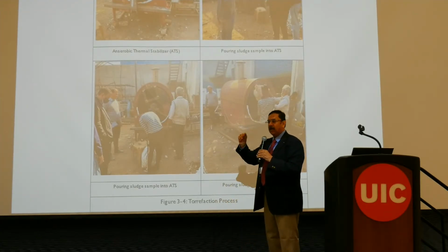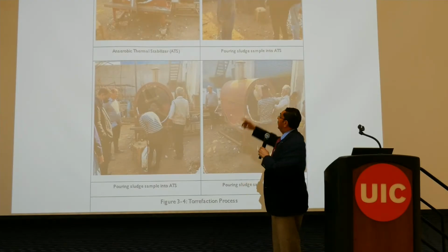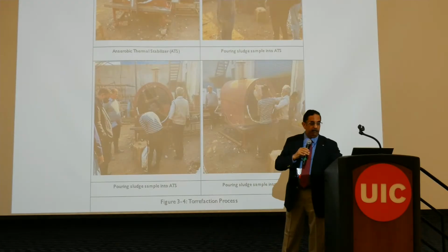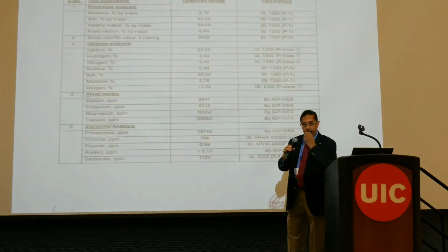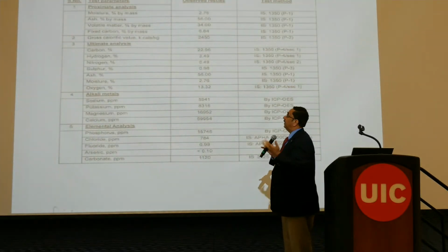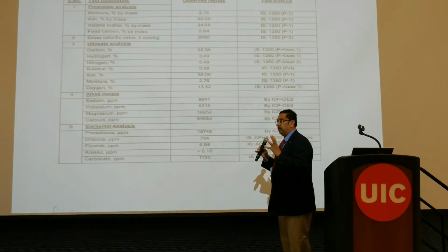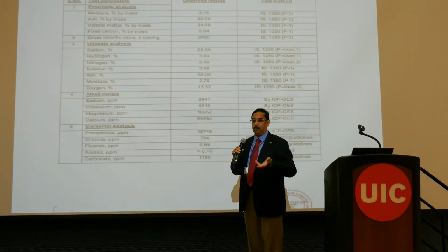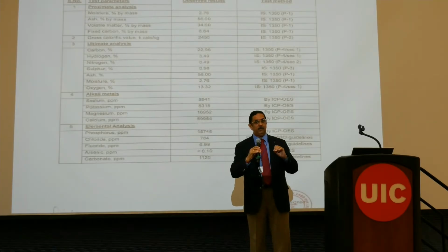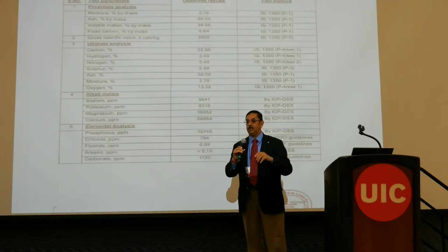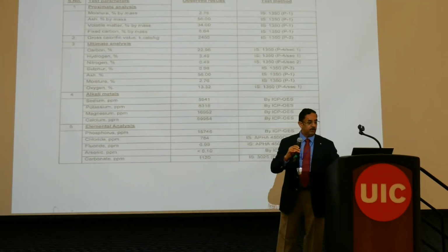I call it slow cooking or slow burning; you can create coal from the sludge in this particular thermal pilot that we built for the city. It gave us very good coal characteristics, somewhere around 2300 to 2500 kilocalories per kg, which was effective enough for the thermal power stations to use as a substitute to coal.